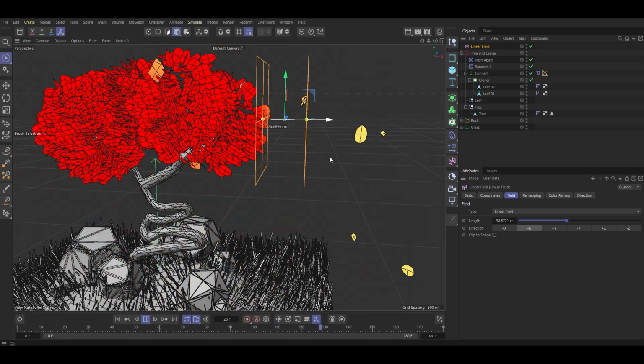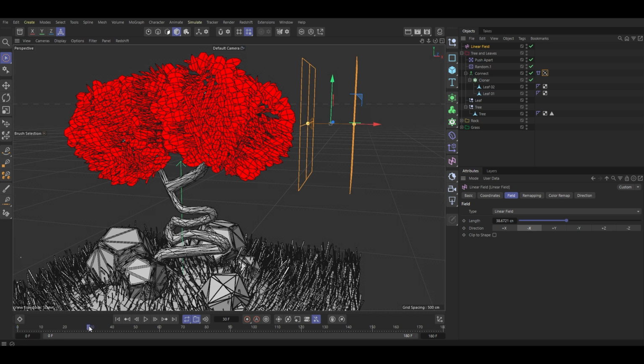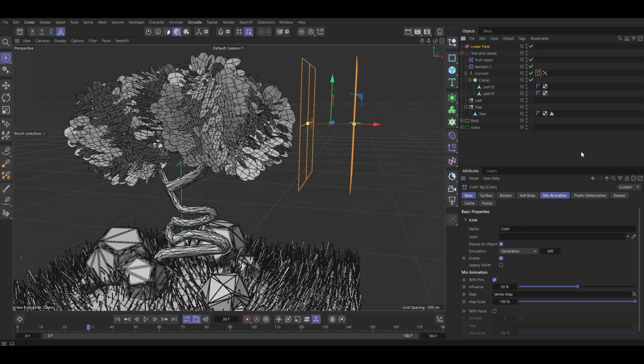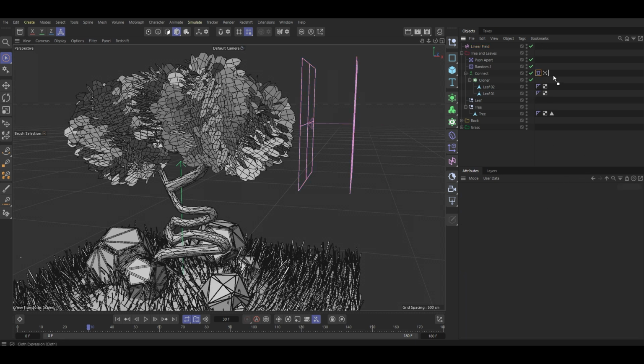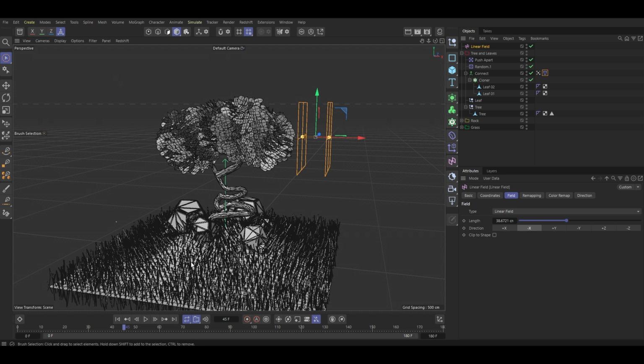Alright, so we are going to animate this now. So for this, we'll start around 30. 30, yes, 30. And make this one. Let's just place this one here. Make the influence 20. Let's just check. Yeah, now it has the dynamics activated, and starting from maybe 45, going to make a keyframe here.